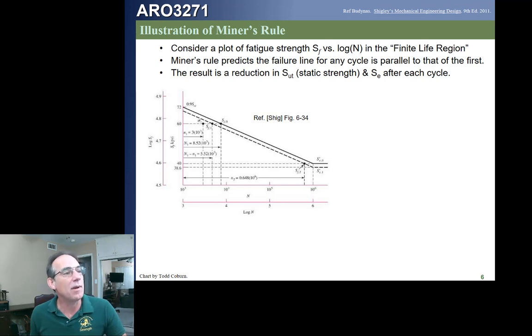Remember we have the SN curve, and we're focused on 10 to the 3 to 10 to the 6 cycles. This is high cycle fatigue. The slope of the curve, going from our point FTU down to our endurance limit, is B, and the intercept is A, but the intercept is at one cycle, not 10 to the 3rd cycle, okay?